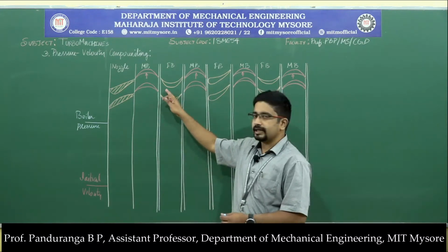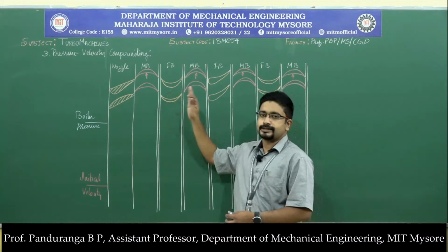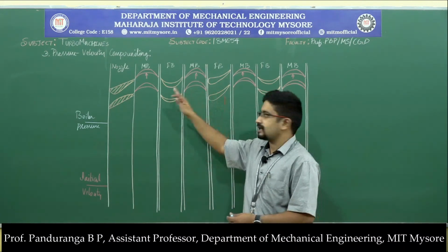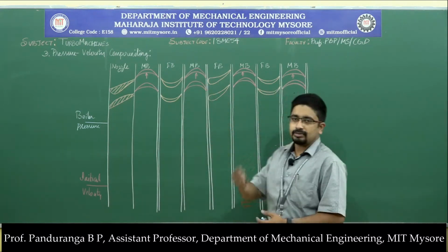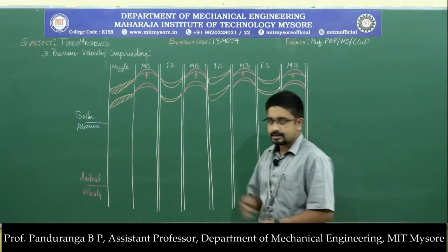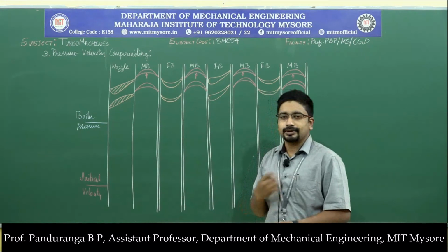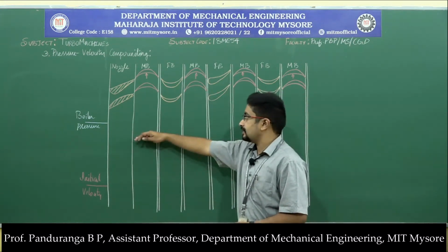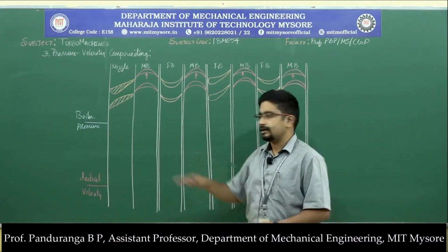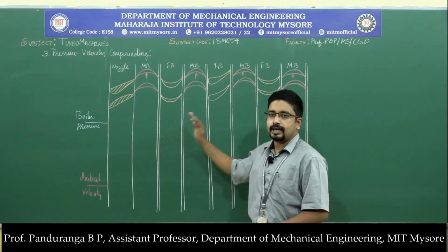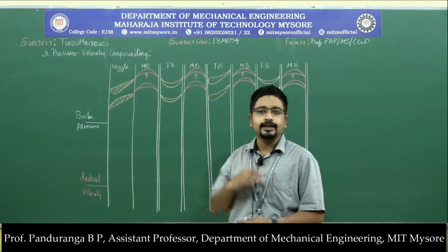If you observe the fixed blade here, it is symmetric in structure. So there is no change in pressure energy as well as kinetic energy as the steam passes through this fixed blade. Then we have the moving blade, where the remaining kinetic energy will be absorbed. So if you remember, here I said a part of the pressure energy will be converted into kinetic energy. So as the steam passes through these three rows of blades, the first row of moving blade, fixed blade, and the second row of moving blade, the pressure of the steam remains relatively high.